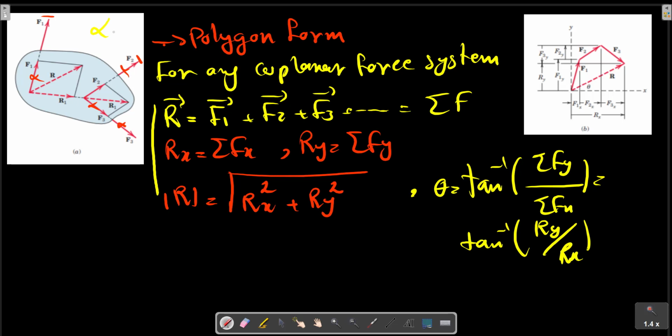For the case of three forces, the sum R1 of F2 and F3 is added to F1, which obtains R. The principle of transmissibility has been used in this process. At first, we continue the force lines of action to obtain the point for F2 and F3. We use R1 and F1 direction to obtain the final answer R. The next section is the algebraic method.